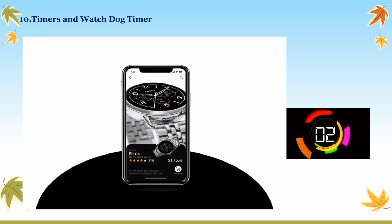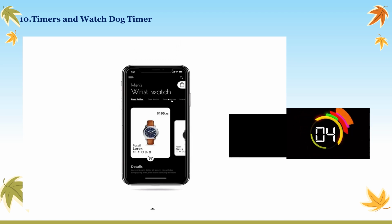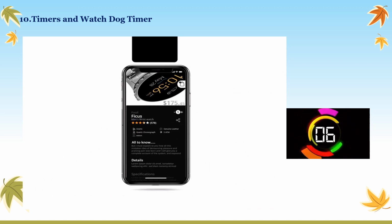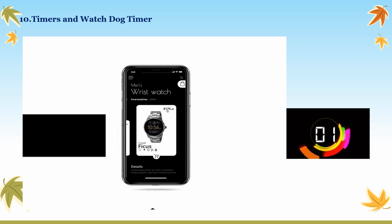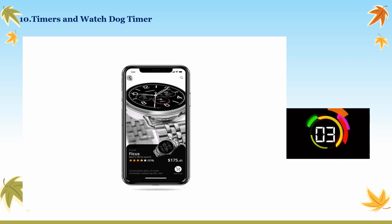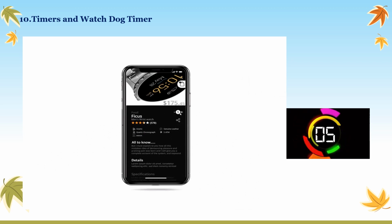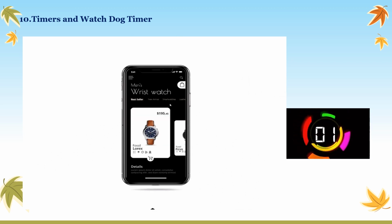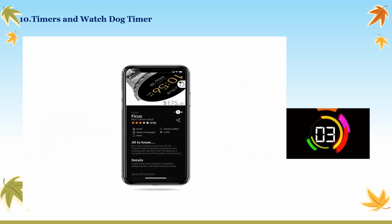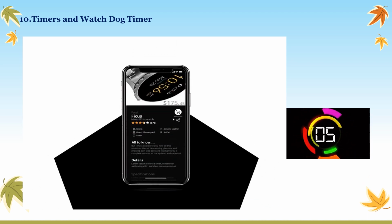An application in a mobile phone is that the display is turned off in case no GUI interaction takes place within a watched time interval. This will save a good amount of battery power. An application in a temperature controller is that if the controller takes no action to switch off the current within a preset watched time interval, the current is switched off, and a warning signal is raised as an indication of controller failure. Failure to switch off current may burst a boiler in which water is heated. If software hangs due to some bug or issue, it helps to reset the system automatically without any human interaction.